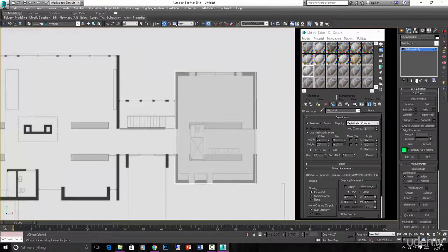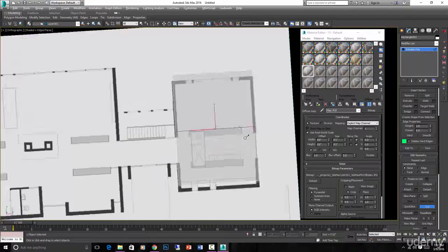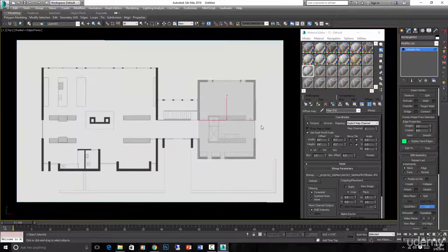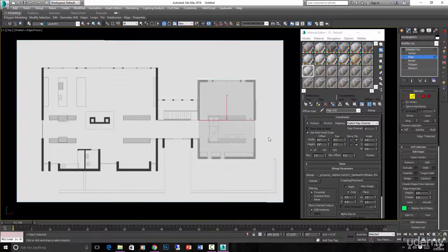it. So what you want to do is you can use the cut tool, but it's not the most reliable tool, but you can see that cut an edge in there. You can also go into edge subobject mode, select two edges like that, and hit connect. You can connect it a certain amount of times. We want one, and then we could drag that into place.